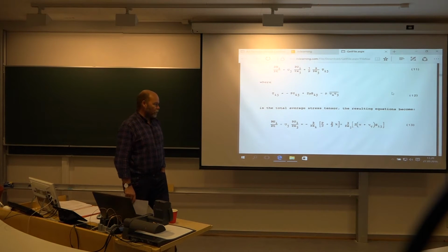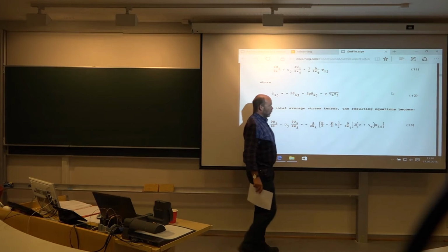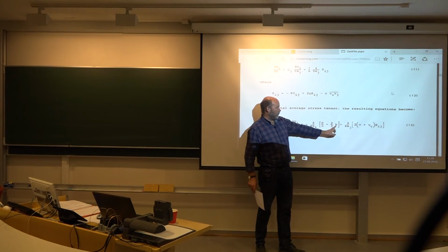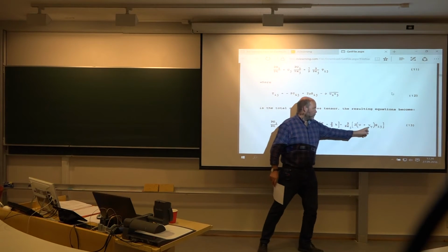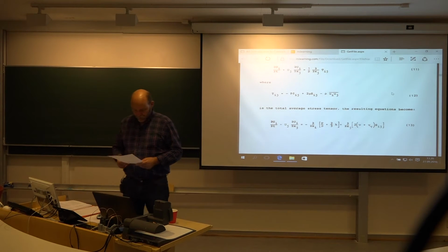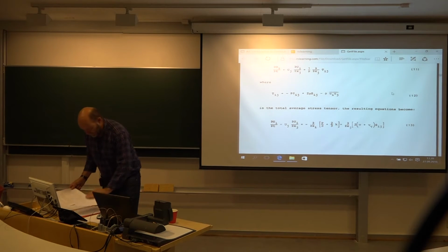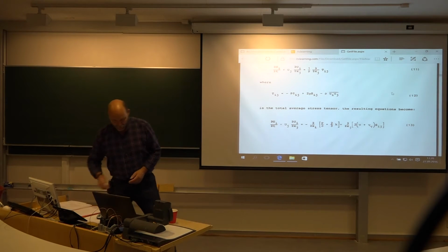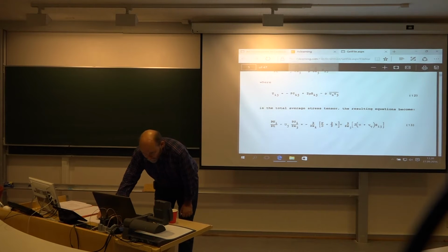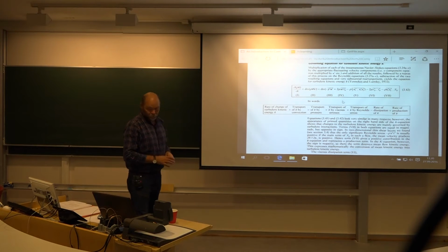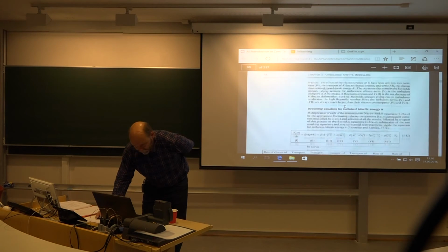Then you had one equation models. Then you needed one quantity that can move, typically the Eddy viscosity. Also, you have one equation models for K that exist. Then you need another equation to couple these two functions together, just an algebraic equation. More interesting will be the family which we call the 2 equation models. That's where we find K epsilon, K omega, the most important turbulence models that we are going to use.